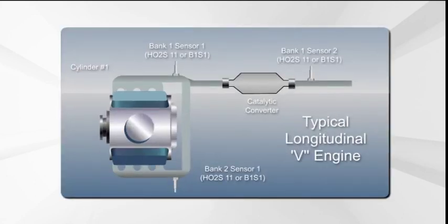Be aware that the oxygen sensors are used as diagnostic inputs for other monitors, such as catalyst efficiency and EGR. Consequently, a stored DTC for a faulty O2 sensor or heating element may prevent the other monitors from running. This is why it's important to always correct component DTCs first whenever multiple codes are stored.